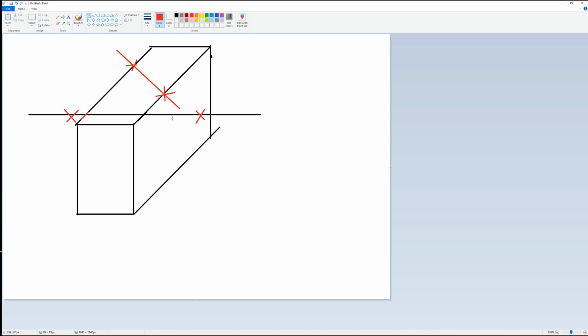But over here we saw visually that our elements are going straight to the wall, and usually MEP elements go in a straight direction. So now the only thing which we need to do is, because the intersection between the solid and the line is just this portion of the line, ask Dynamo to tell us what is the length of this line.